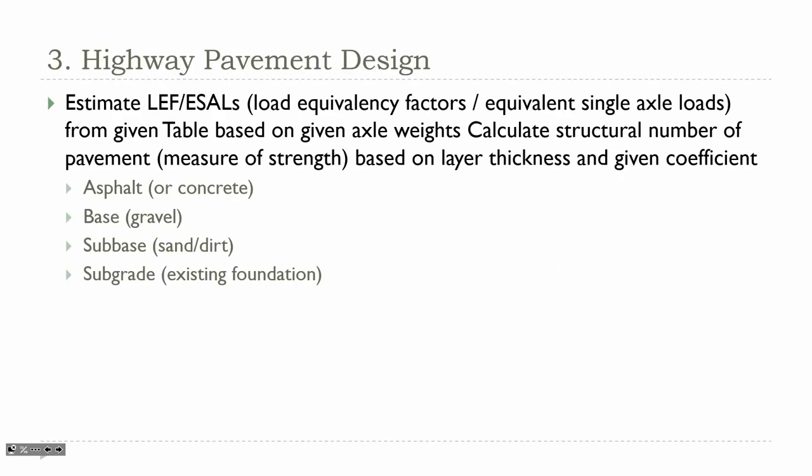Pavement design. Again, this is something else we covered in transportation. The load equivalency factor, or ESAL, I think the FE exam uses the LEF, load equivalency factor. We also refer to it as an ESAL in 342. And there is a table on the next slide that gives you what those load equivalency factors are for a given axle weight. There should be another bullet here. This should be on the next line.